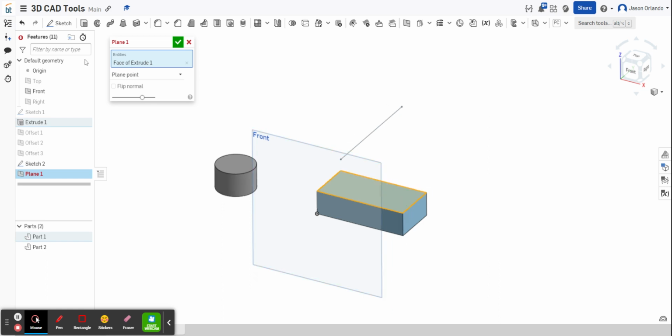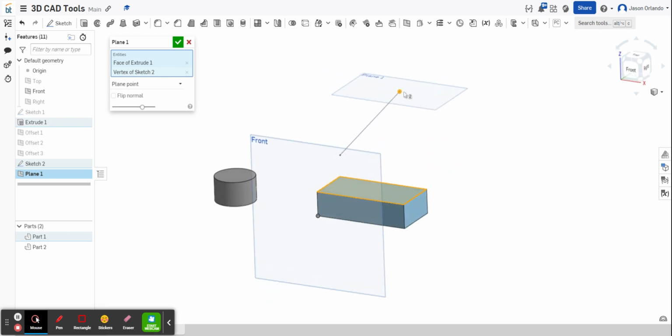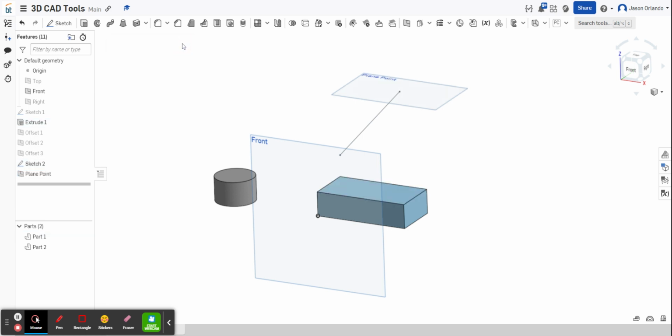The point comes in, it's plane and point, to specify basically that offset distance. I have to be parallel to this plane, but I have to go through a point that I select. So if I choose this point up here at the very top, that plane has to be horizontal like that one, parallel to it. Those are parallel planes, and it has to pass through that point. So that is plane, point. Parallel to plane through a point. Just like that.